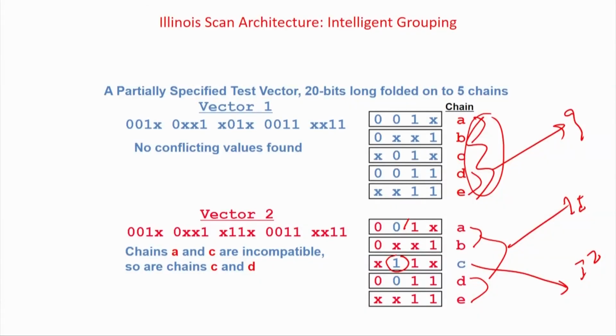So how exactly you partition, and what is the most optimal way of partitioning, so that the number of pinouts is minimized as well as there is no fault remain untestable, and we can solve this by the compatibility purpose. This is an NP complete, very tough computational problem, and you cannot find an exact algorithm to do it. It will take exponential amount of time. So there are a lot of heuristics to do it.